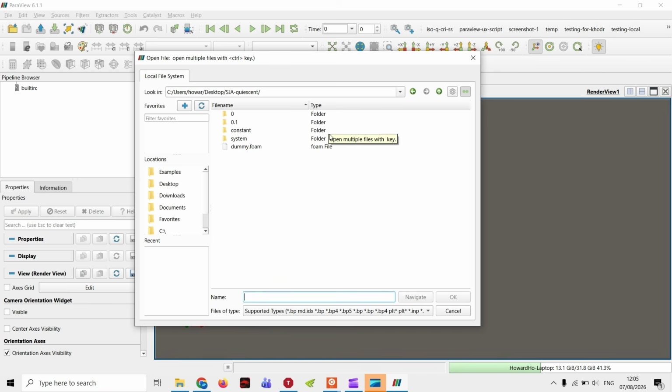Now, this is a standard OpenFOAM case layout. You have the initial zero directory, and you have output, constant, system. Now, when you run OpenFOAM, it's not going to have this file called dummy.foam, because OpenFOAM doesn't need it. This is a dummy to tell ParaView that this is an OpenFOAM folder, and ParaView is almost tailored for OpenFOAM. It'll still load other data, but to unlock its full power, OpenFOAM data is best. You can just type touch dummy.foam in the command console or Ubuntu terminal, or any name ending in .foam. As long as the file ends in .foam, ParaView will recognize it.